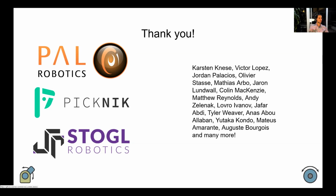Okay, I've got a professor who wants to work with real-time ROS, and a robot that was designed for Indigo and uses ROS industrial control, not ROS control. I'm wondering, would I need to re-implement the entire hardware interface, or just translate some messages in the proper format?